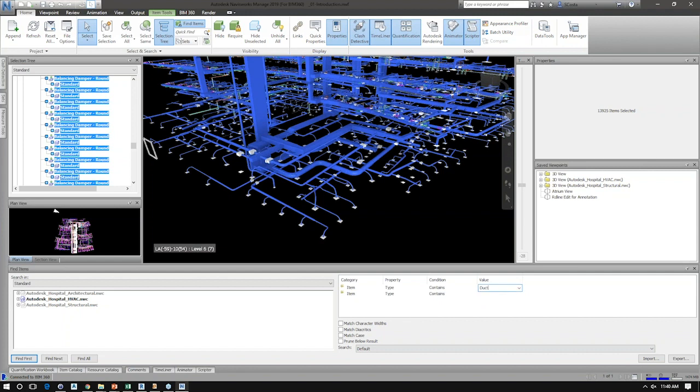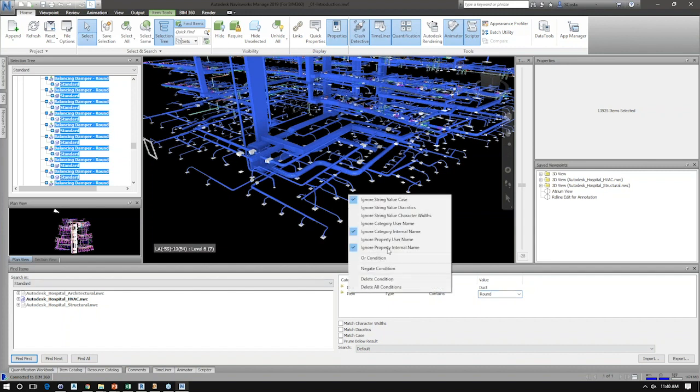The first selection is grabbing duct. And Navisworks is particularly finicky about where you click. And now I can choose round. And what it's doing is it's building a logical sequence where it uses an AND condition, right? By default, it's an AND condition.